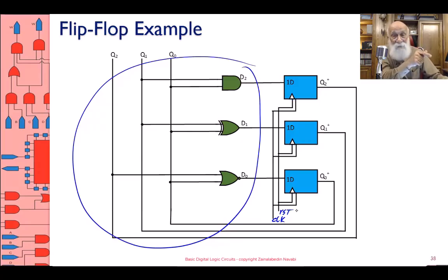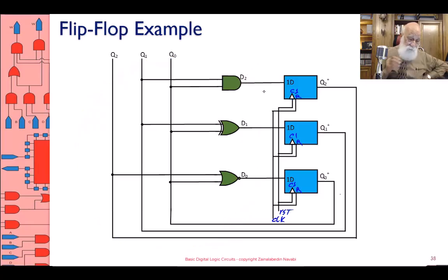They only participate in the operation, and that has to do with the type of flip-flop that you use. If you want to be complete, this is C1, those are 1D, and these are the resets. And my counter is working and counting from 000 to 001. And if I ever want to reset it asynchronously, this is how I do it.